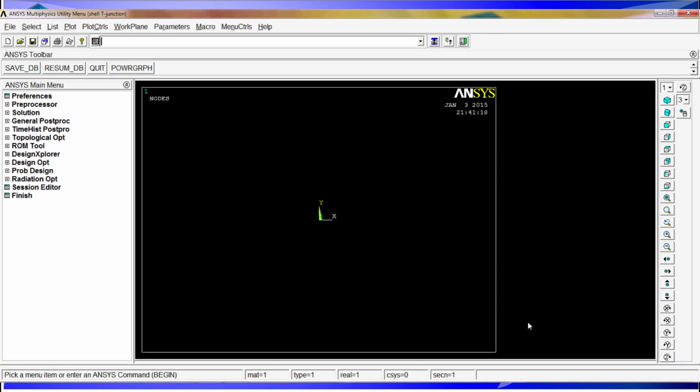We'll continue with the Ansys environment, and for this tutorial we will use a slightly different approach. As we said, the transversal beam is going to be a 40 by 40 by 3 millimeters. If we do it through the extraction of the medium fiber, that will be a 37 by 37 millimeters with a thickness of 3 millimeters. So what we'll do today is use a different approach.